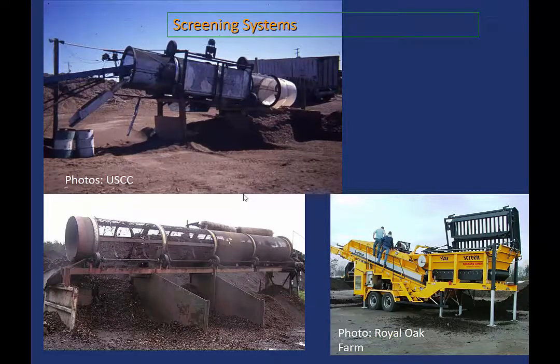Again, screening isn't necessarily required, but it depends on what you have in there. So if we're taking especially a lot of food waste, we probably want to screen out some of those materials. On campus, for example, when we go to our compost facility, there's forks in there, and there's rubber bands, and there's plastic bags, and so we definitely have to screen. So screening isn't required, but it depends on how you're selling it and what you're taking in, and what screening processes you're going to use.